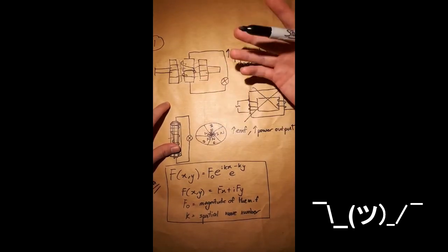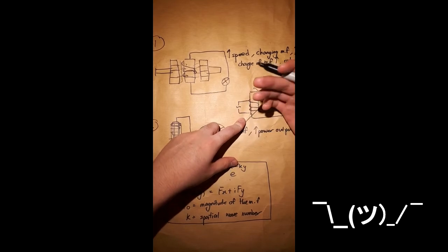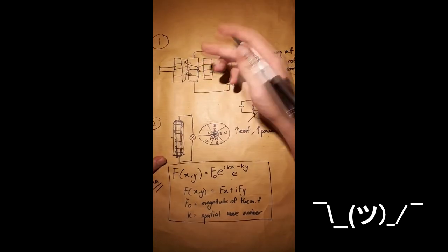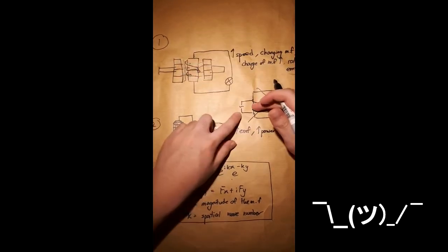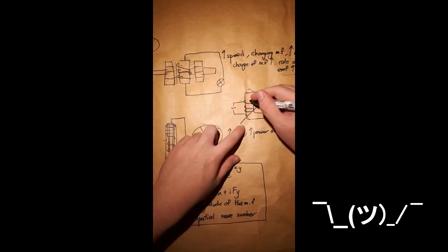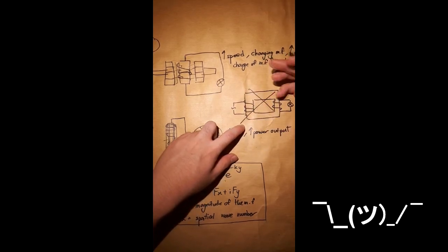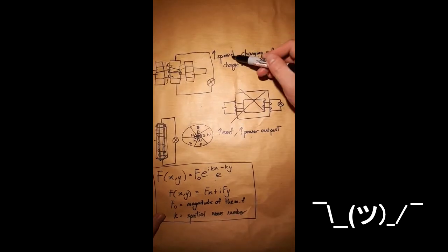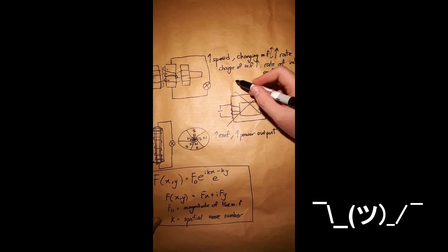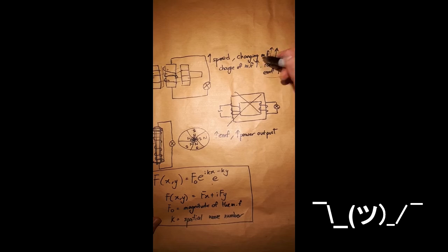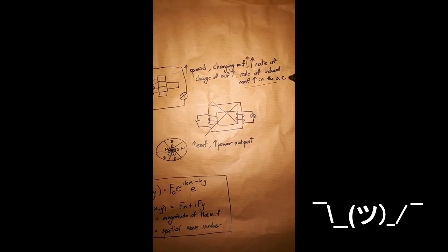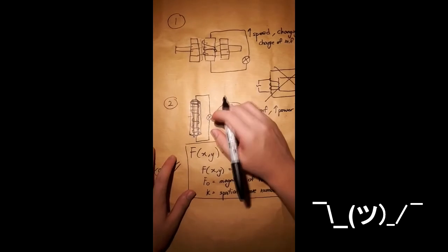This is really good because we don't even need our basic transformer power supply, which is AC, anymore, because we can just rotate this Halbach array arrangement at really high speed and we will already get that alternating magnetic field, not by using alternating current, where the direction of current is different every time. So this is the advantage. At high speed, the rate of change of magnetic field increases, and the rate of induced EMF in the secondary coil increases.